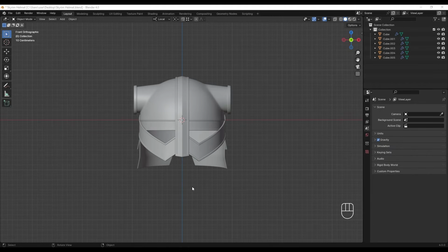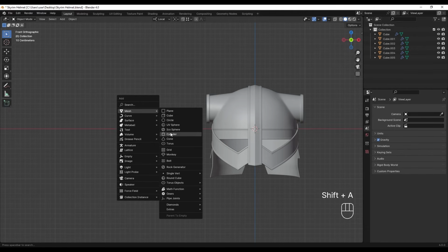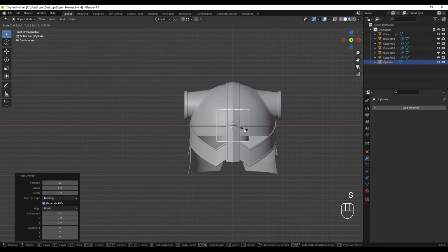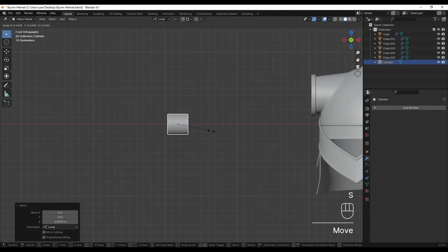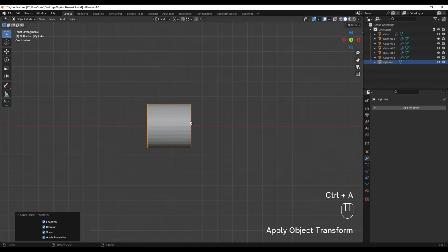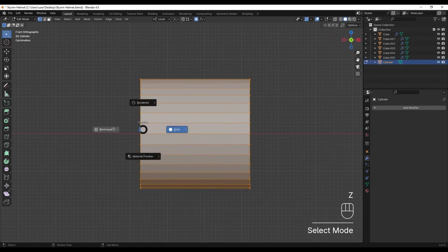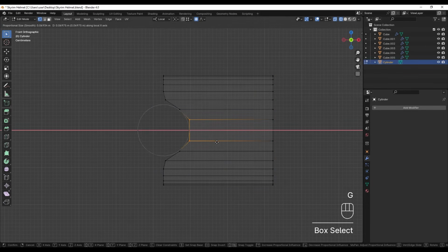So now let's create the horn. We're almost going to use the same technique we did in our last tutorial about the chain of the Vampire Killer whip. So let's do this again. I'm going to add a cylinder without any cap, and I scale this down, rotate this 90 degrees, and put this here. We're scaling this down a little bit, and I'm going to apply all the transforms. I'm going to turn on proportional editing and select the vertex, go to wireframe and select these and move this back. You can scroll your mouse to increase the zone of your moving.